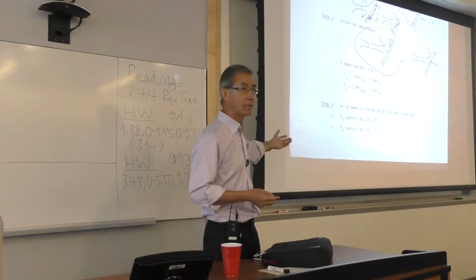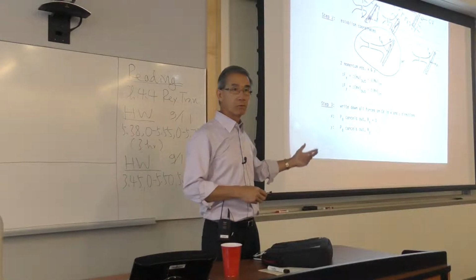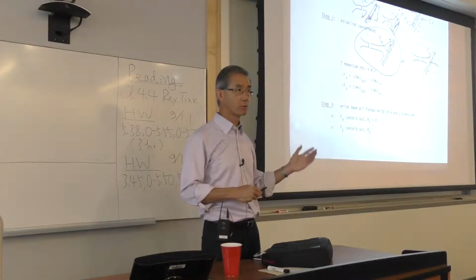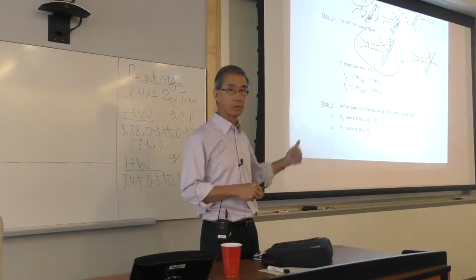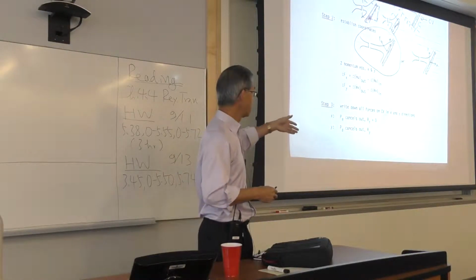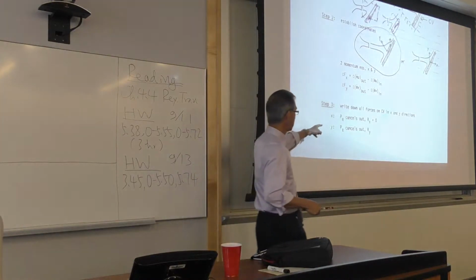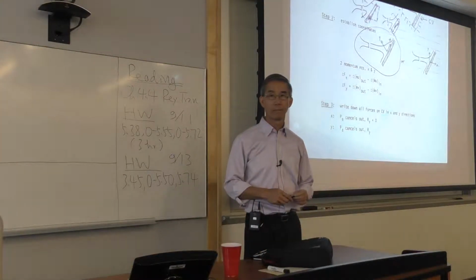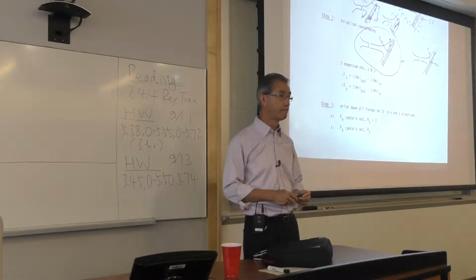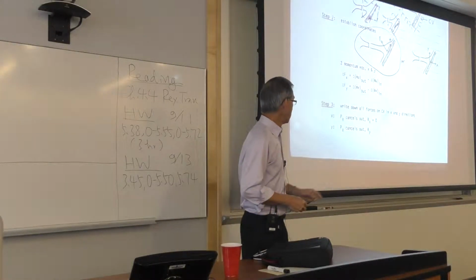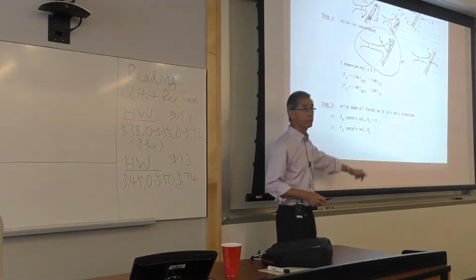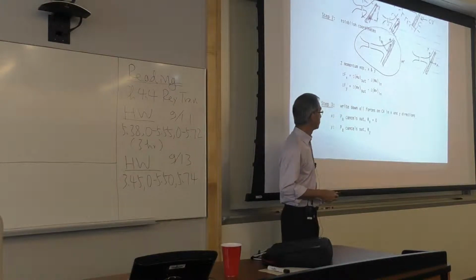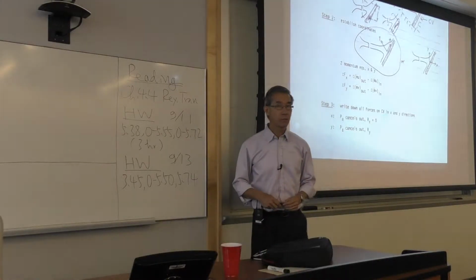Do you understand why I give you that? Half an hour ago, I drew you a diagram of an arbitrary shaped control volume versus a circle, and it's for this reason. No matter how I cut it, the net pressure forces cancel out in both directions. Let me stop and make sure you understand that. Do you? Okay? The other forces are the anchoring force, and again, if I assume them in a different direction, will the answer change?